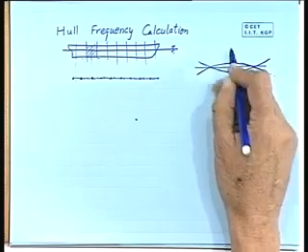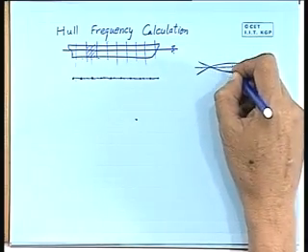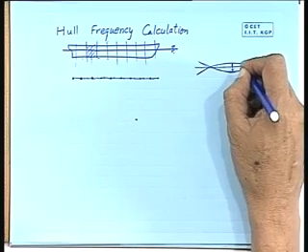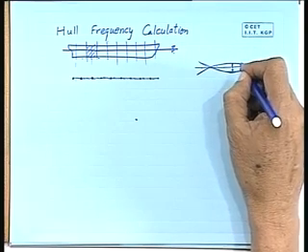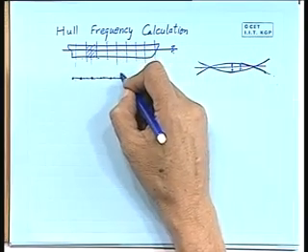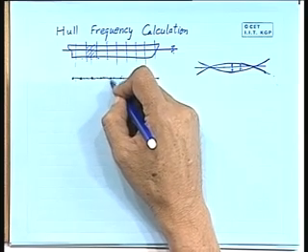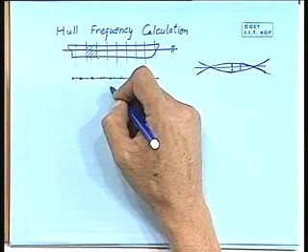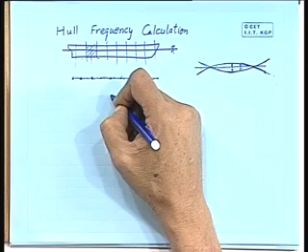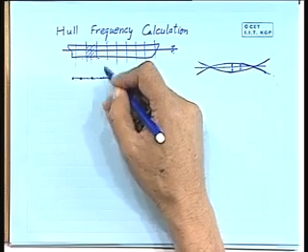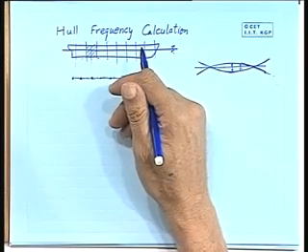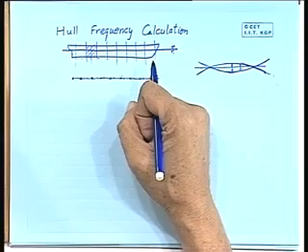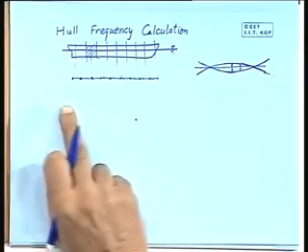Now with this acceleration, at every point you can find out what the acceleration is up and down for this movement. What is the acceleration at this point for this movement? Now this corresponds to some mass here, and therefore you get the acceleration of that particular mass, and therefore you get the inertia force of that particular mass. Okay. So now this inertia force is going to give you some sort of a loading onto this beam.